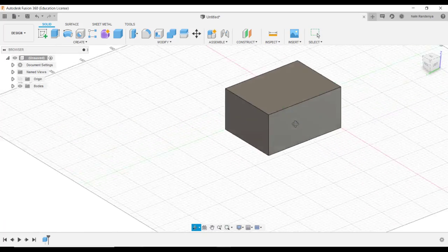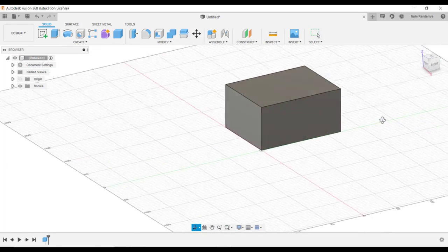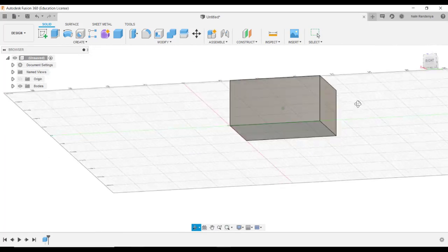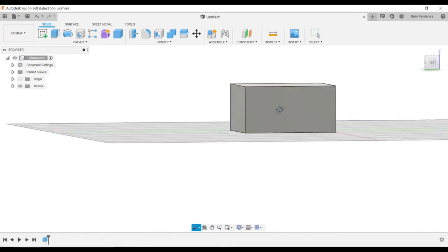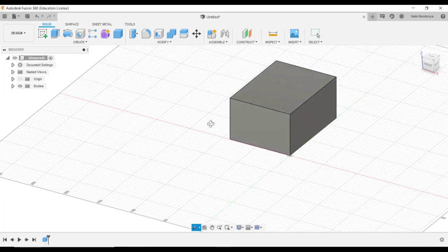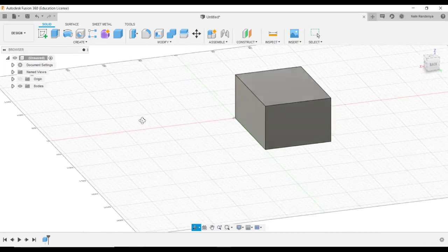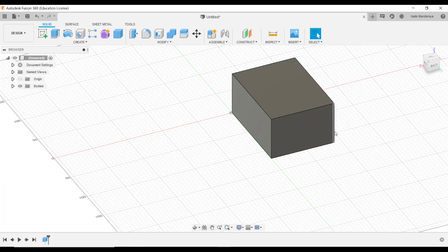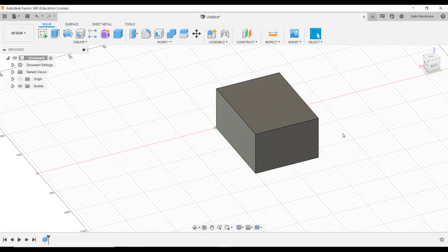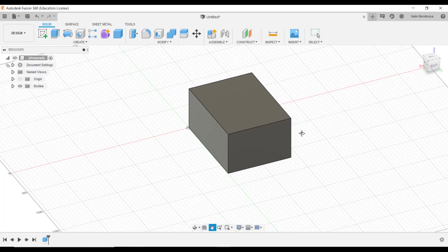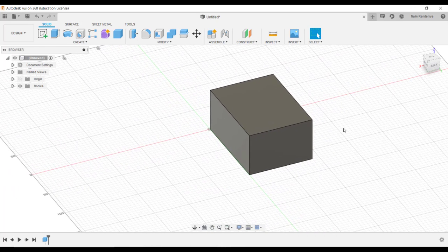We call that orbiting, actually, orbiting around the model. When you're working on a 3D model, you need to look from different angles. So this is a very important navigation option, I would say. That's simply done with, again, the mouse. But remember what we did for panning, press and hold the middle mouse button. You do the same thing while pressing and holding the shift key on the keyboard and the middle mouse button of the mouse. Keyboard shift button and the middle mouse button.